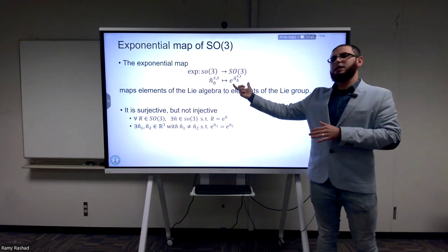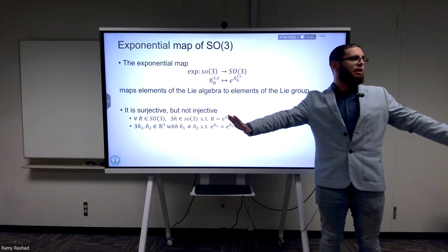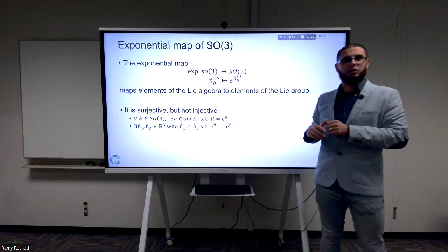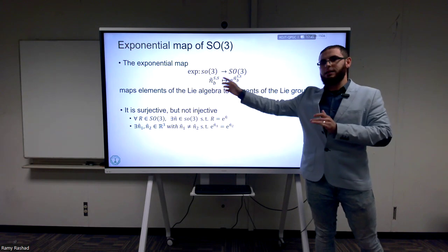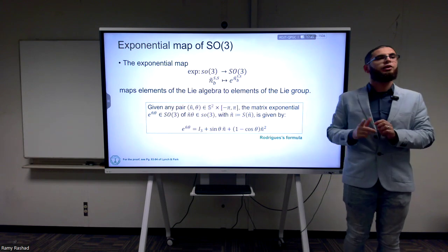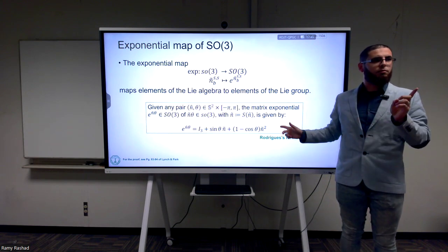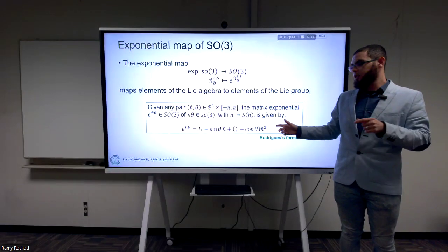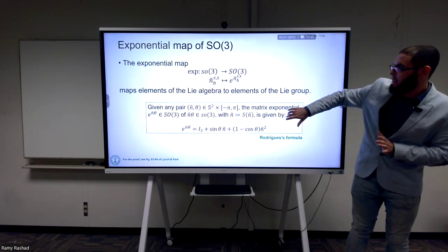Okay, this matrix exponential, we said, is an infinite series expansion of I plus, again, the expression that we had before. But because this is a skew-symmetric matrix, it has a very nice closed form solution. And this closed form solution is known as Rodrigues' formula. Okay? Who here is familiar with this expression? Rodrigues' formula? 1, 2, okay. So 3.